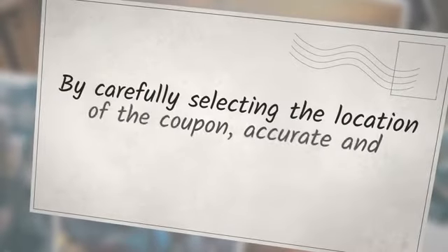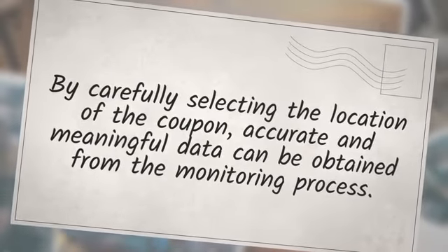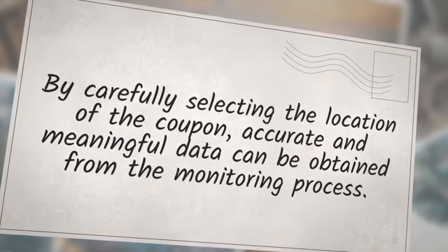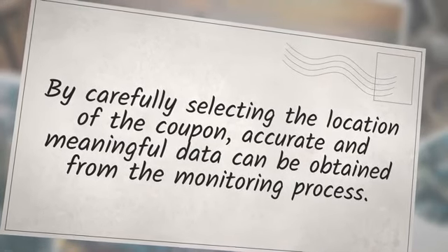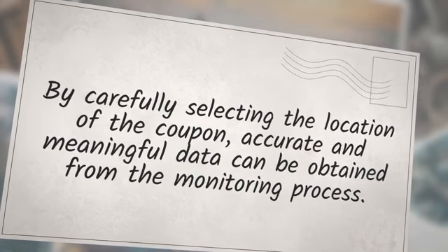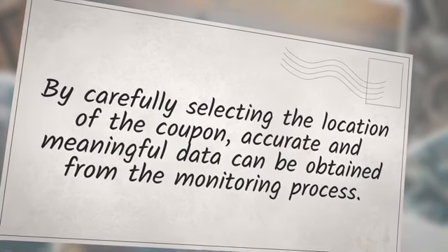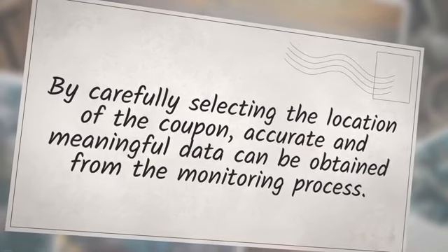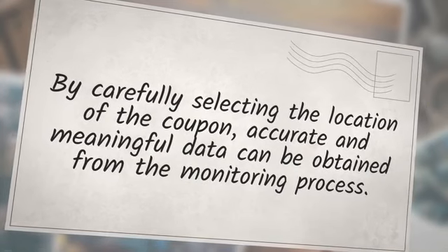Overall, the location of the corrosion coupon should be selected based on a thorough understanding of the system being monitored and the specific factors that may impact the corrosion rates. By carefully selecting the location of the coupon, accurate and meaningful data can be obtained from the monitoring process.